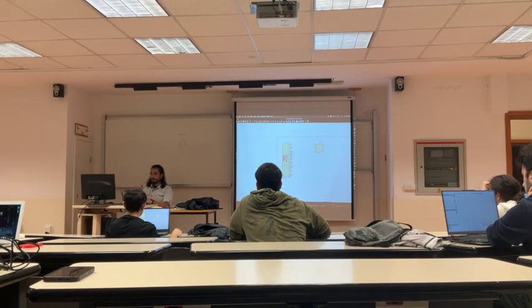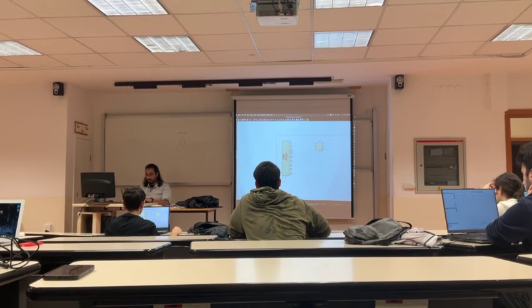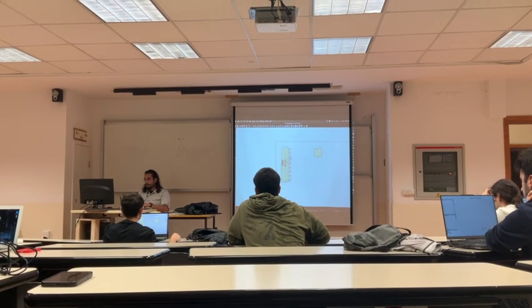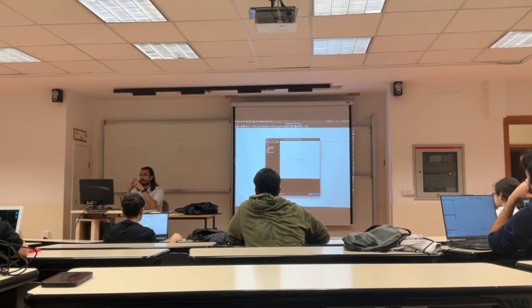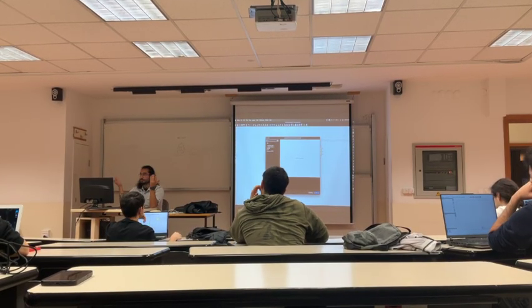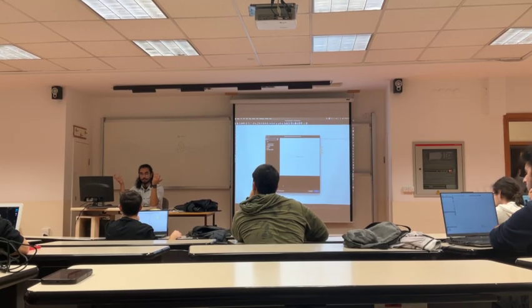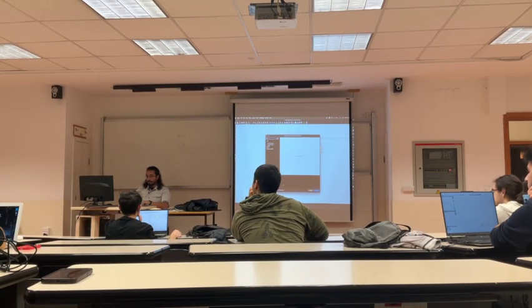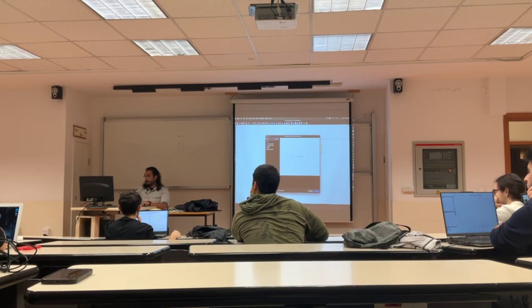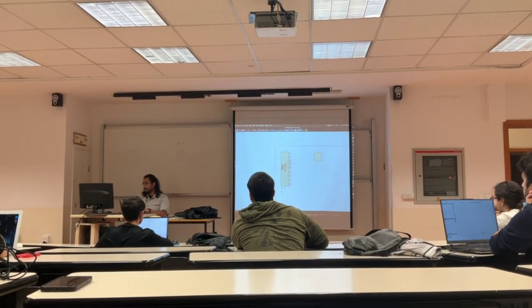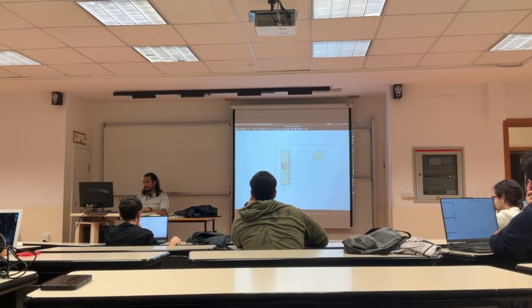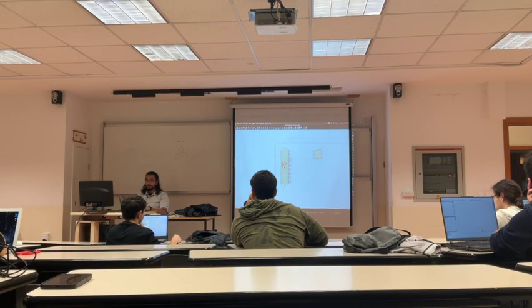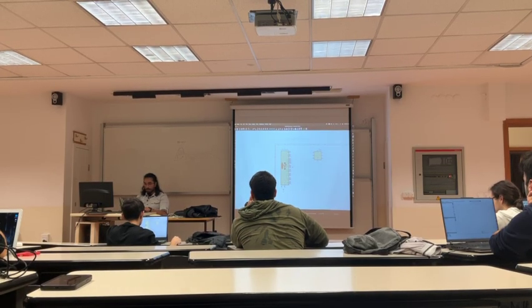So shield is the protective layer around the Type-C receptacle. I am going to first click on P. This is power symbols. So power symbols are like grounds, 5 volts, which is the things that power your PCB. So we want to label them separately. I click on P. I type ground. I get the global ground. I use generally global ground. You don't need to do much more than that. Generally, I connect ground and shield together. Yep. And yeah, we almost done with the receptacle.